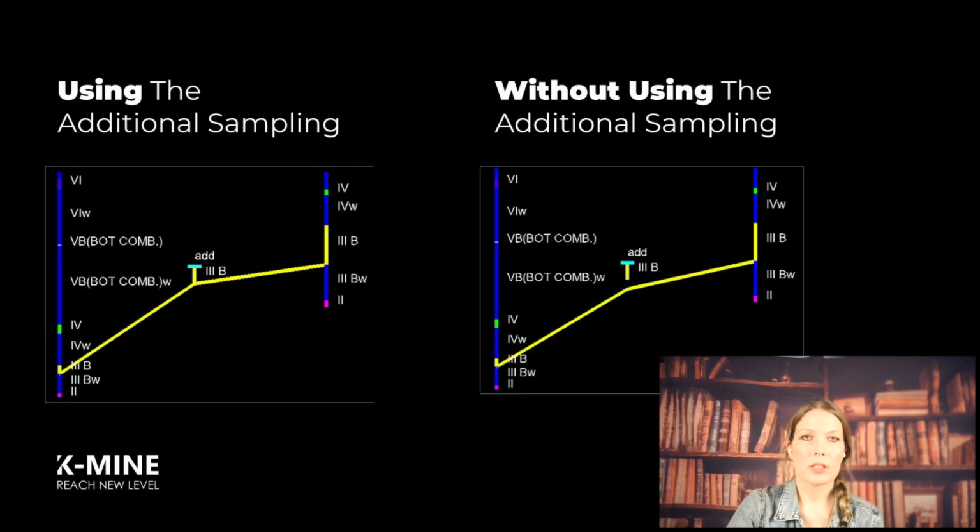With additional sampling applied to the selected type of workings, the actual positions of the top and bottom of seam intersections are taken into account. For example, on the left figure, the bottom of guide seam 3B, the blue line, is shown when the drill hole add is used as additional sampling. In this case, the algorithm directly considers the actual intersection of drill hole add with the bottom of guide seam 3B in 3D space, without interpolating the seam thickness based on adjacent drill holes.